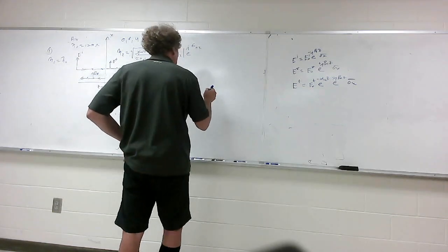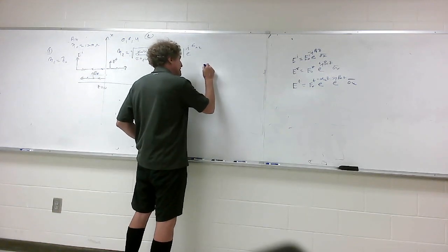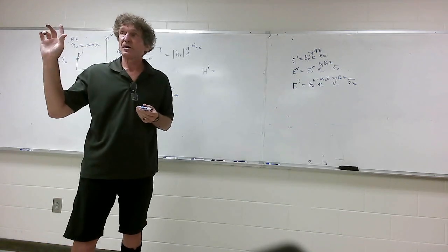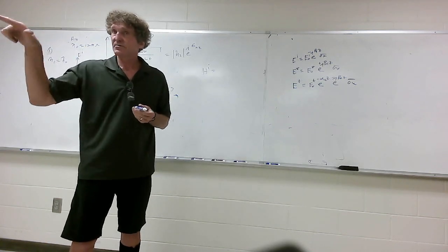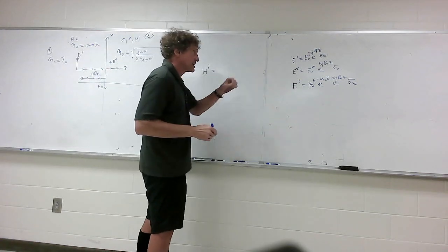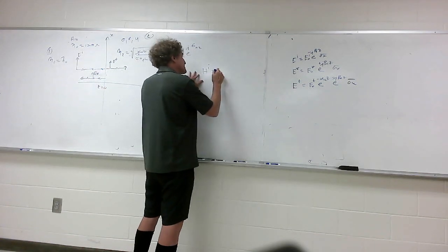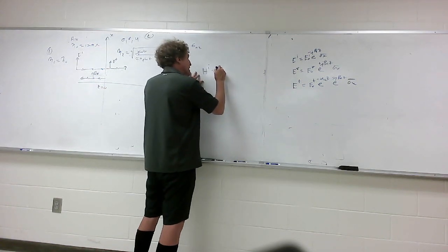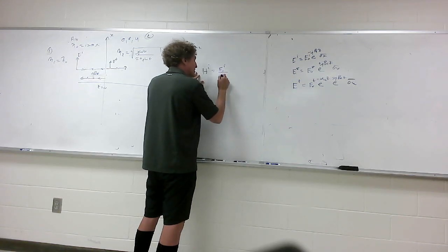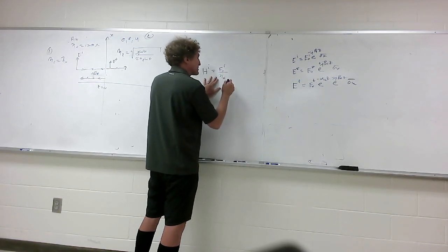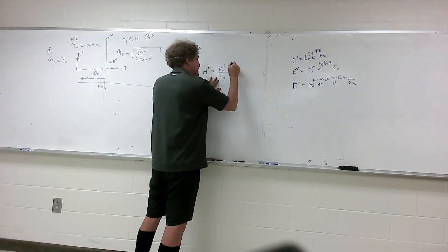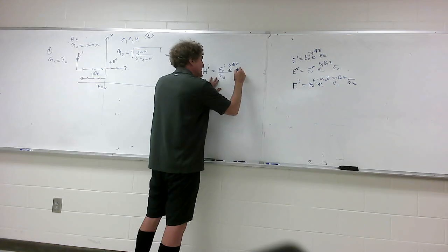You're going to have an H incident, and I'm just going to tell you what it is because I told you the right-hand rule, right? E cross H, direction of propagation. We see the E field's in the X direction. It's propagating in Z. Therefore, this is going to be equal to some E naught incident over eta, or eta naught, if you will, because I'm saying this is free space, times e^(-jβ1 z), in the a_y direction.